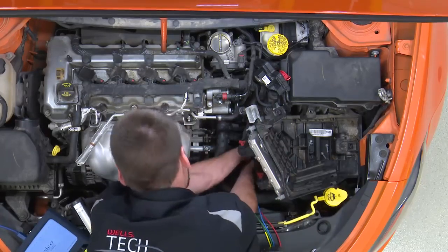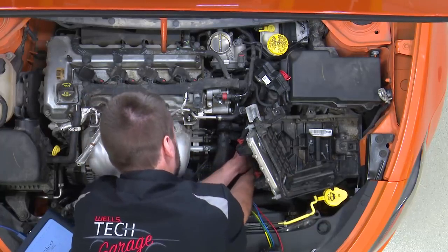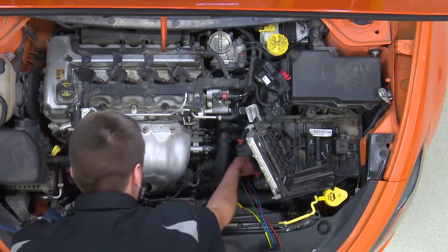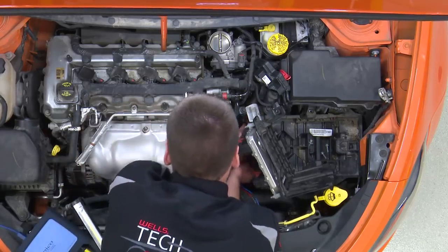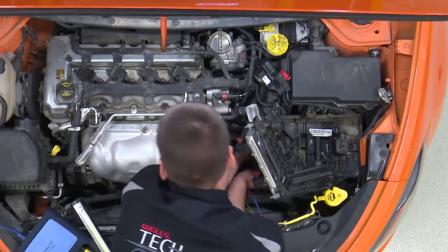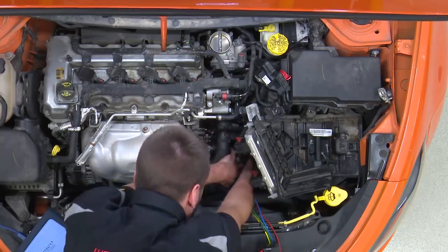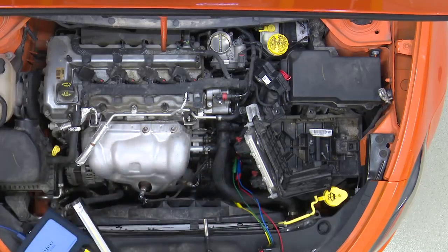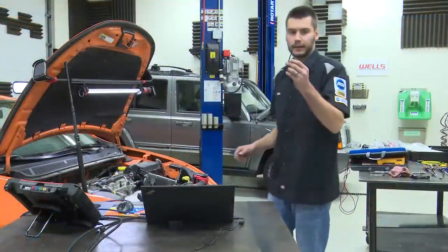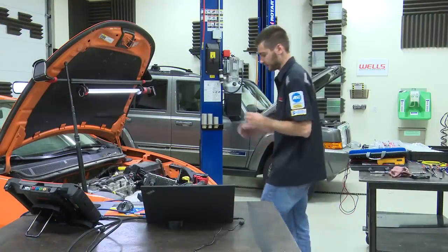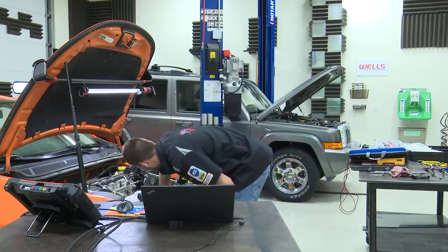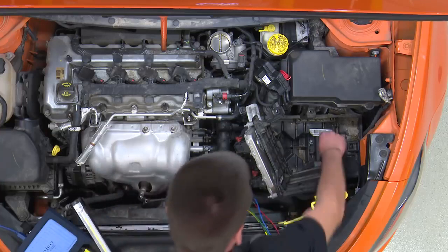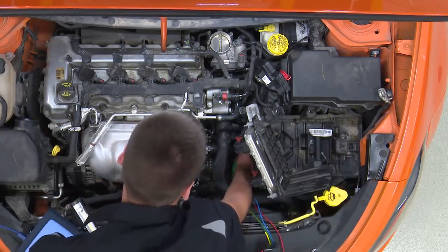Well, I definitely am not making time on this job today. There's our old one. And our new one. And now what I'm going to use, guys, I got a little Allen wrench here. I'm just going to line up the two holes between the shift lever piece, or shift cable piece, and the new sensor. Make sure they're lined up as I tighten the bolts down. Because what that's going to do, that's going to line this thing up for the neutral position.